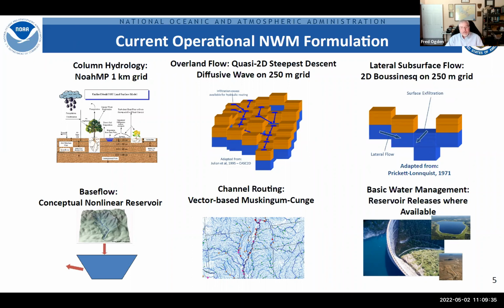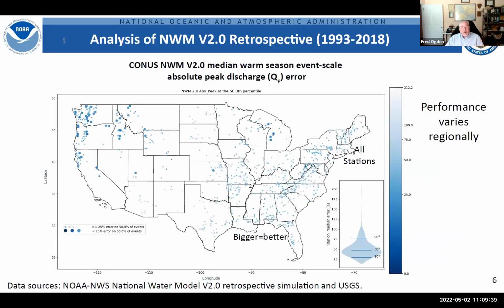available. Next slide. When we look at how the National Water Model performs, the Weather Service's priority right now is producing inundated area maps based on forecast stream flows for the entire NHD network. And if you look at how it's performing, inundated area is very highly correlated with peak flow discharge estimates.